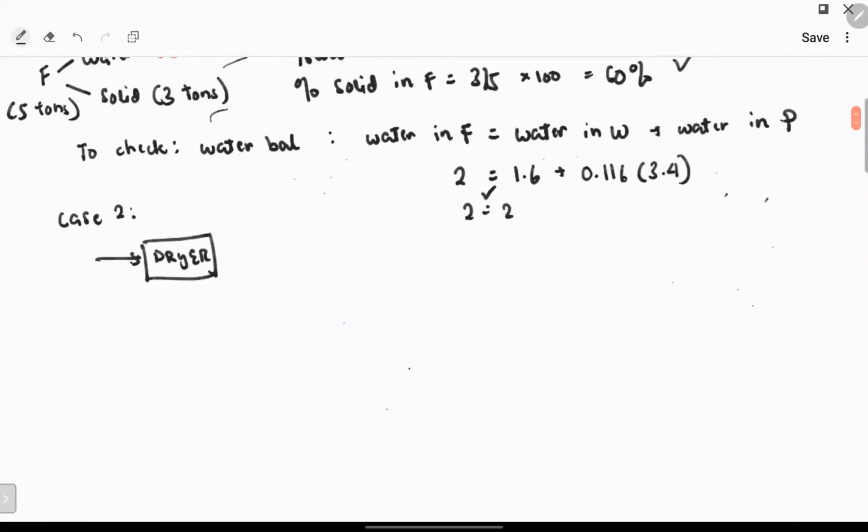It's the same thing. You have an entering feed, or an inlet, and then my P, and that's water. In this case, we don't know F and P, but what we know is W, which is 1.6 tons. Kasi, according to the problem, it should remove a constant amount of water for any drying case for this particular equipment. Constant lang yung nare-remove niyang water.